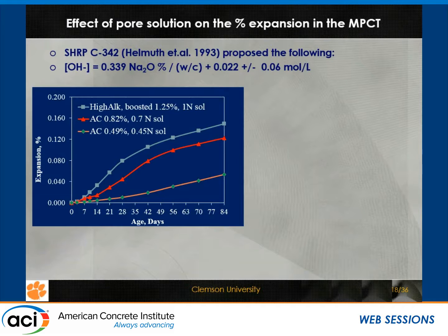But this is as close to avoiding the leaching, if you will, as you can get: submerging the samples in a soak solution that is very similar to what the pore solution is made of. So you don't have any leaching. The flip side of it is that now you have a fairly large reservoir of pore solution that is feeding into the sample as the reactions take place. But it's definitely a little bit more conservative than not having anything at all or doing other things.